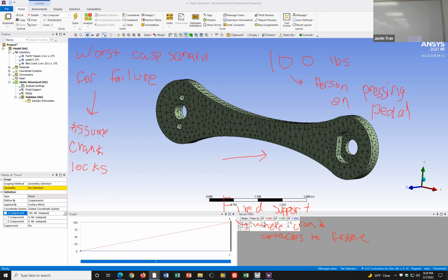The reason most of the book examples are like that is because that's the only statically determinate setup. Rollers are usually really difficult to do for trusses because you have to angle them perfectly.